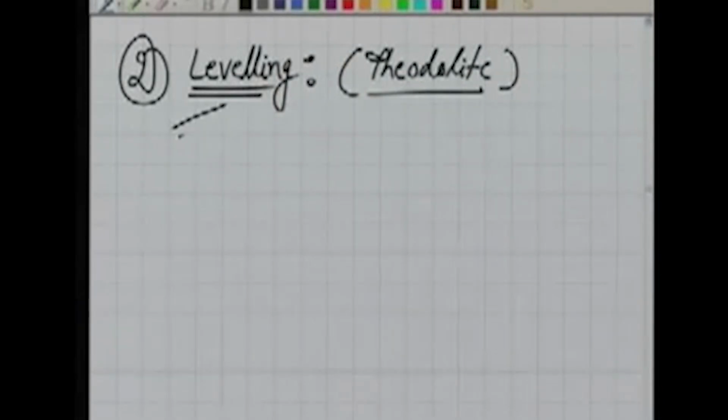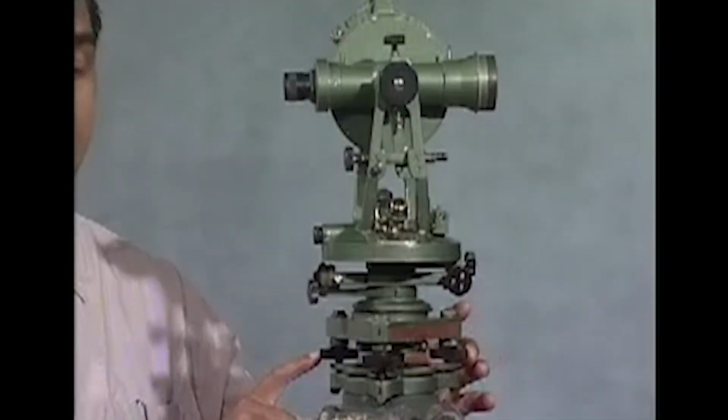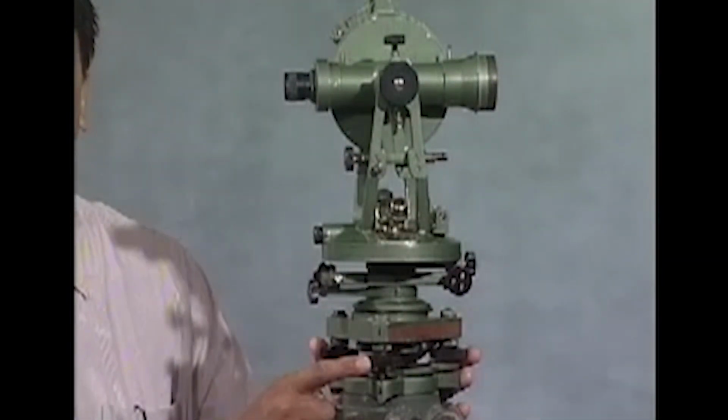Okay, now our theodolite is on top of the tripod. We fit it. Now what is next? The next step is leveling of the theodolite, because so far our tripod head is leveled and centered. Well, how to do that? For the leveling of the theodolite, we have three leveling screws, as you can see here, 1, 2 or 3, and these are also called foot screws.